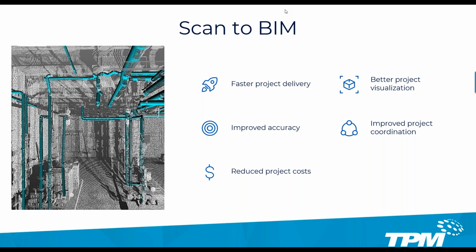There are quite a few things that we can do once we have that laser scanning data as well. There's deviation analysis that can be done based on walls moving. There's the ability to turn that scan data into a model to create a facilities maintenance model. You can do that even if the project really wasn't done in BIM technically. So you can go back in and scan that project, get everything modeled, and produce that facilities maintenance model for your team. It allows for floor flatness analysis and really captures anything historic.